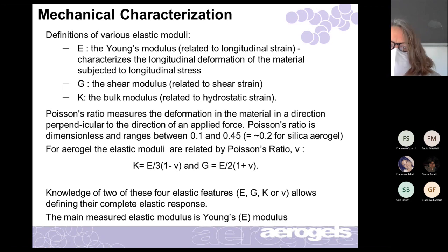So there are different elastic moduli that are used. The symbol E is used to represent the Young's modulus. It characterizes the longitudinal deformation of the material subject to longitudinal stress. So as I pull something, how much does it deform based on how much I pull it apart?